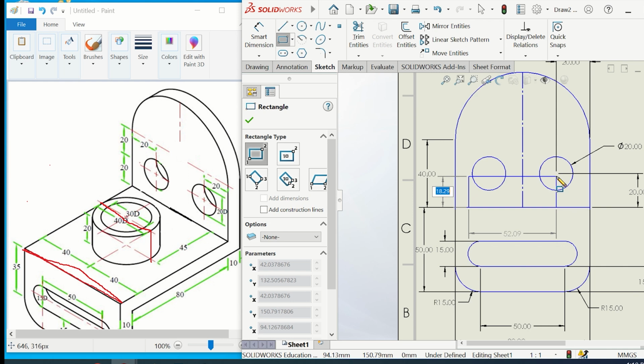I don't want it to get stuck on the center point of any of these circles, because I'm not sure if it's going to end up being stuck there or not. So I'm going to input again the height, which is 20 units. This, of course, takes it to the level of the centers, and the width, which is 50.